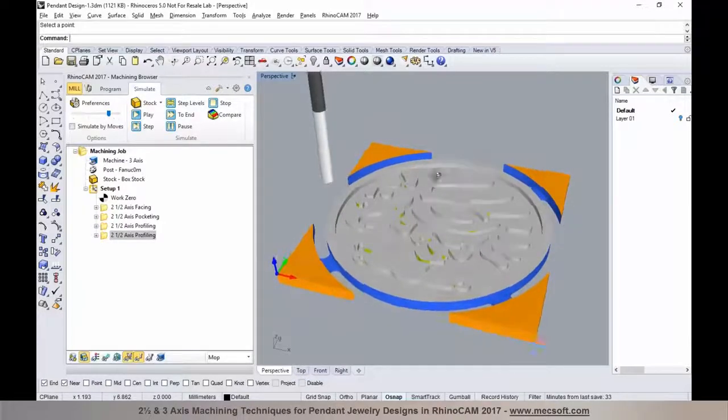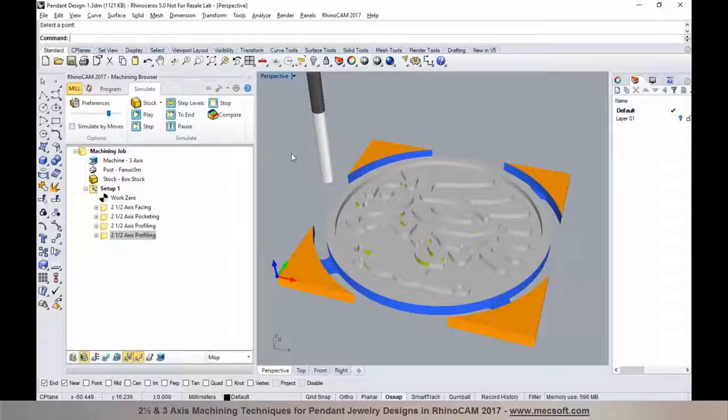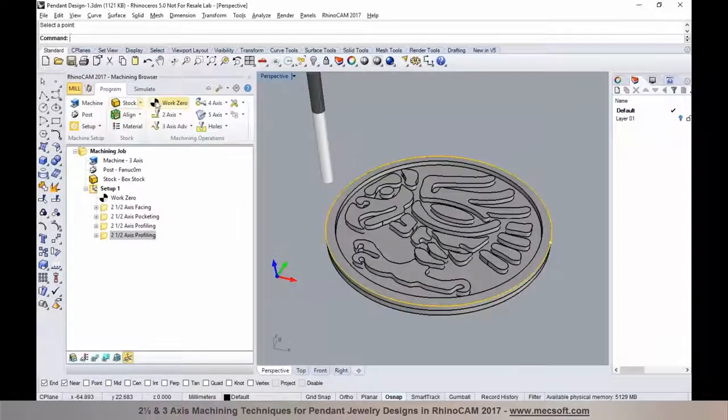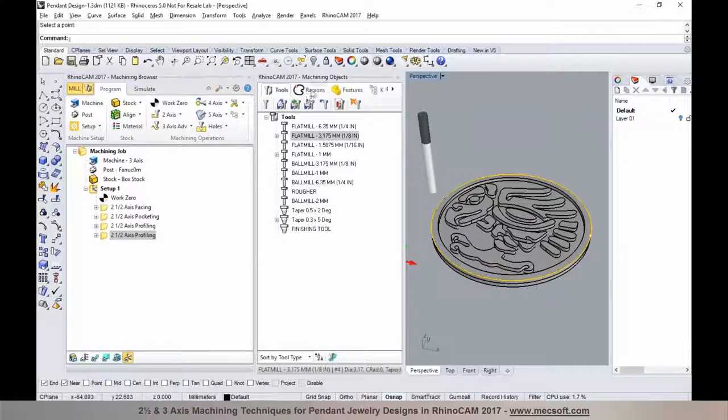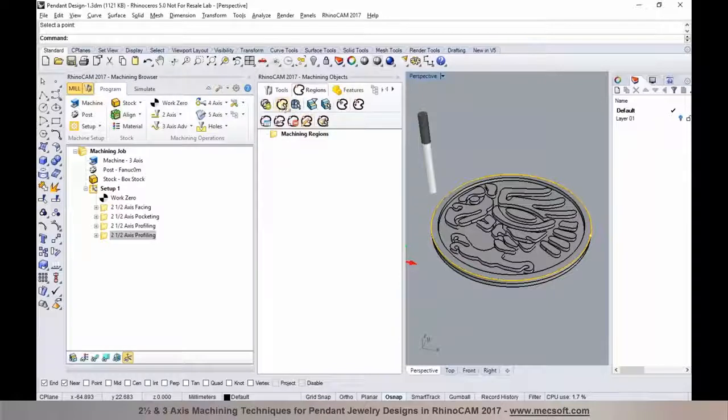Now we could also do manual bridge points to precisely select where you'd like the bridges to be placed. This can be done by creating a machining region under the regions tab, and then you can add bridge points, where you can do manual bridge point selection. You can also edit bridge points and selection. For more information on how to create these machining regions and bridge points, you can refer to the help section, or you can also refer to one of the recordings of past webinars.